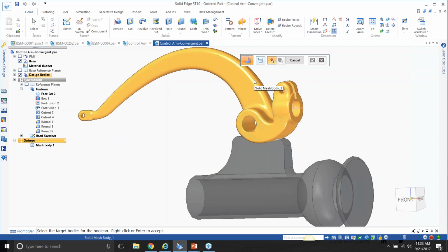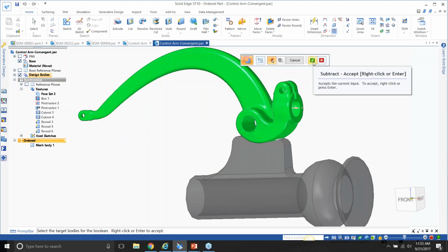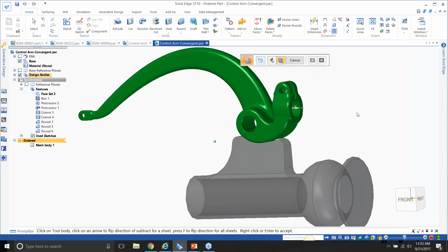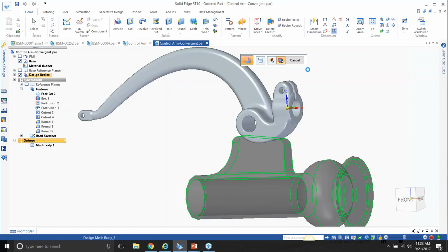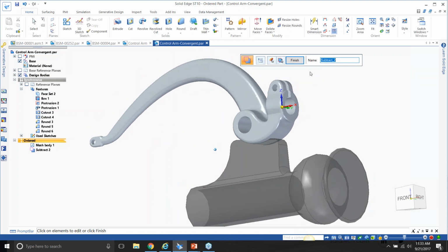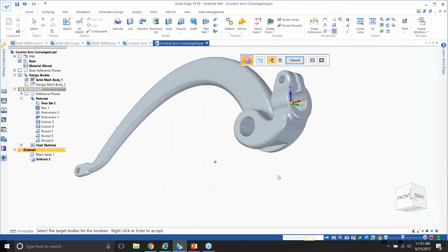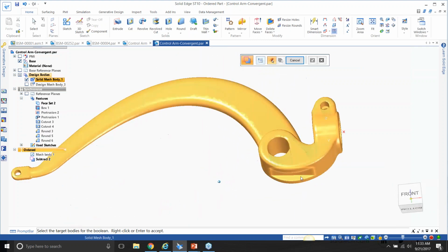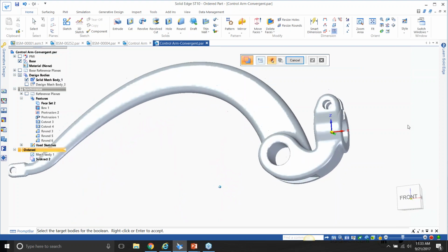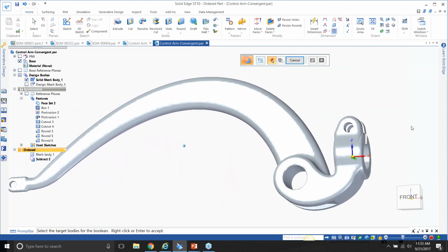So I can click my STL file, or STL part or mesh part, hit select. I can use that B-rep model, hit select, and just like that, if you guys noticed, hit finish, the B-rep model cut into the STL file, STL model or mesh model, as you can tell right here. And due to convergent modeling, that's all possible. And you can do other things.